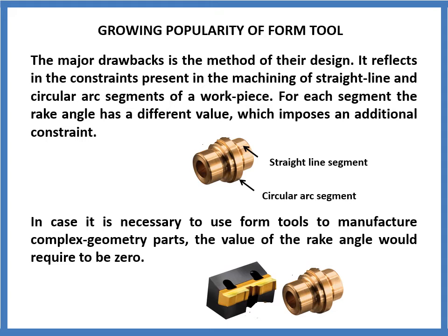More than the rake angle, the clearance angle provided to these form tools will be significantly important. We will be doing various numericals on both flat form and circular form tools having clearance angle alpha, and not only having 0 rake angle, there will be designs where the rake angles can be made positive or negative.